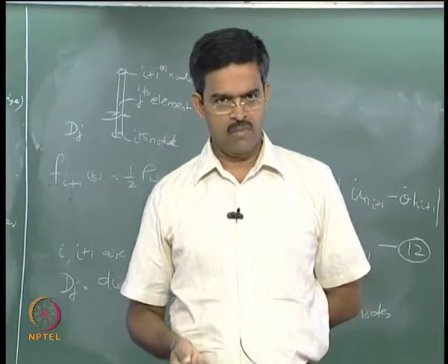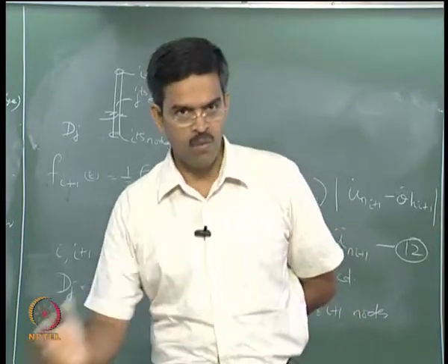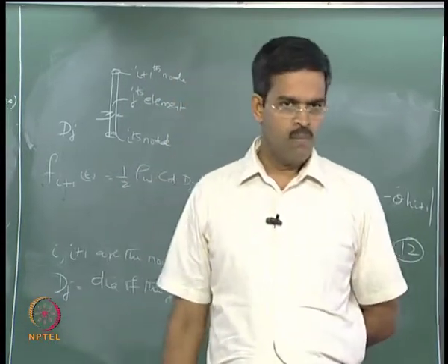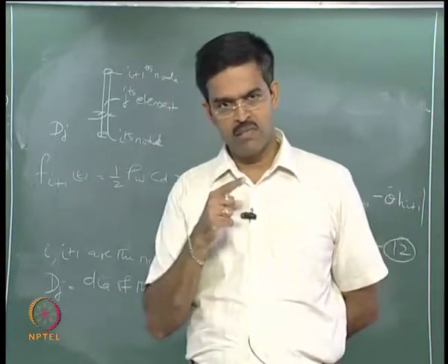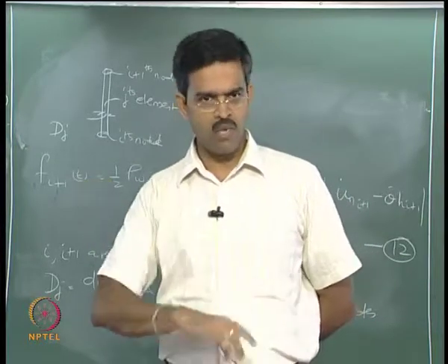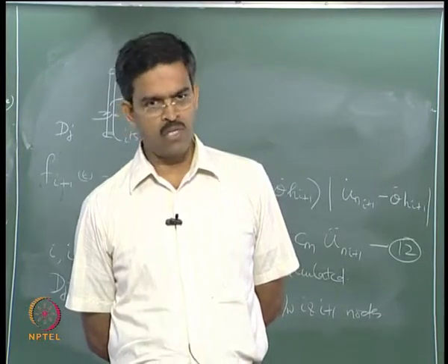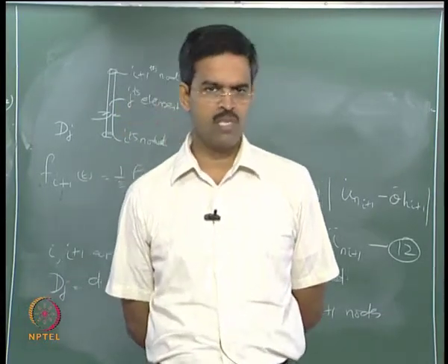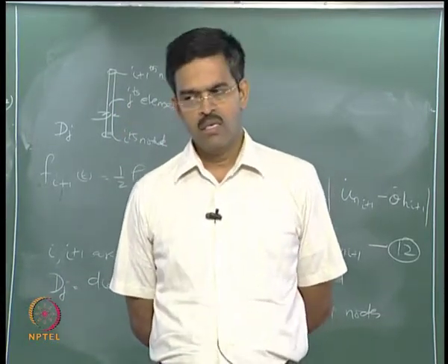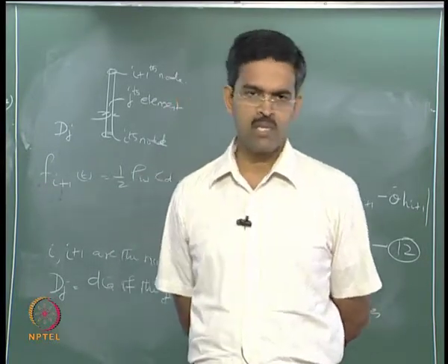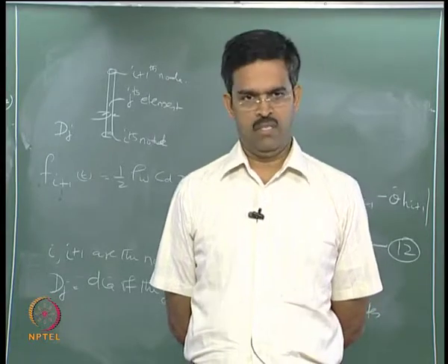I will check whether the maximum displacement is beyond the permissible value, and so on. From this I can easily connect this to the stability of the model also, which I am not touching here, can be done. So the outcome of the solution of the equation of motion, to be precise, will be time history of the rotational degree of freedom or power spectral density function of theta.